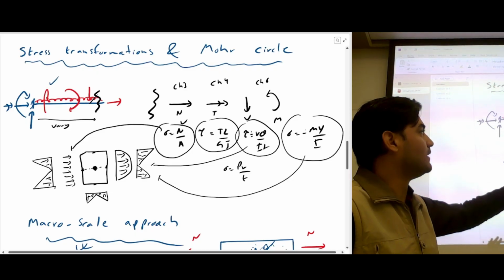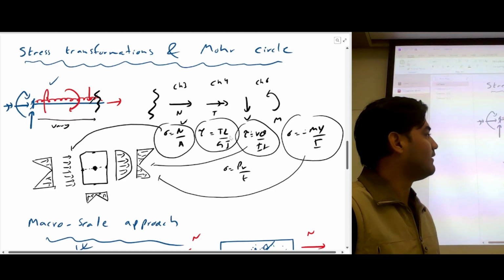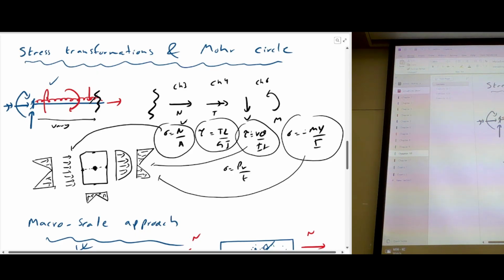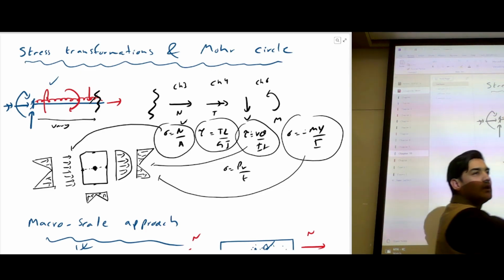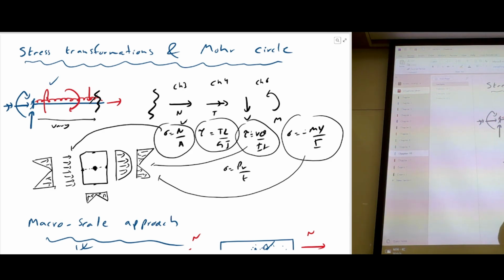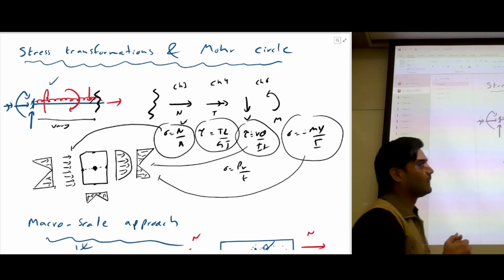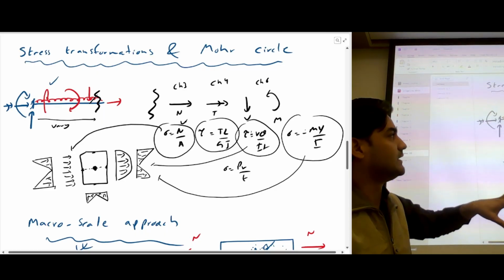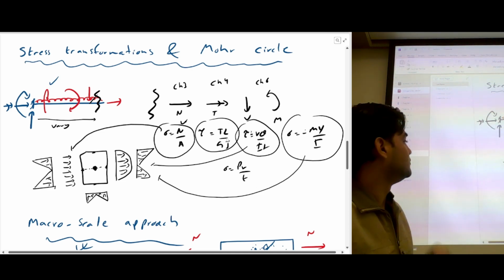We're going to talk about this on the combined loading chapter, but this chapter is about stress transformation. And why this chapter is important, because once we get the combined effect, basically we can get the combined effect of all those stresses in terms of axial stresses and shear stresses, right? But the way we look, these axial stresses and shear stresses can be different based on our selected coordinate system. So we need to do the stress transformation because we divide the combined effect of all those stresses in axial stresses and torsion stresses. But when you rotate the stress element, some of the axial stresses may go to the shear stresses, some of the shear stresses may go into the axial stresses. So we have to figure out the maximum of either of those and how we do this. So basically, we are trying to calculate the maximum stresses by considering all these. And the best way to do this is using Mohr circle.